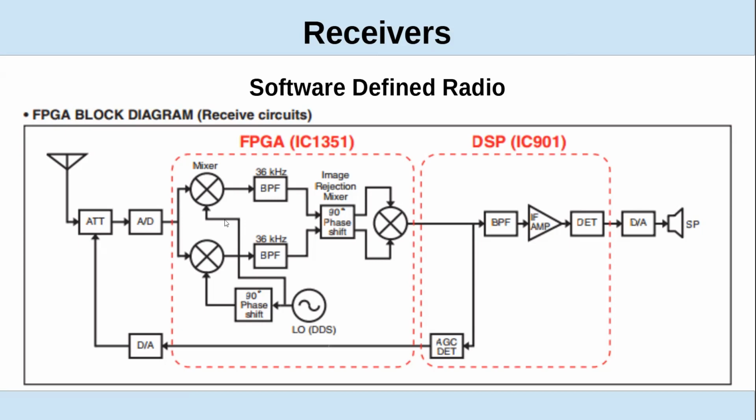So if you want to amplify it, you've got a sample that, say, is 5. You multiply 5 by 2. Now it's 10. I've got a gain of 2. It's this simple digital multiplication. And the same thing for the filtering. It's slightly more than multiplication, but it's just mathematics that you're doing digitally. Well, the beauty of the digital is you're not having the losses through your filters. And you can make filters that look like square wave.